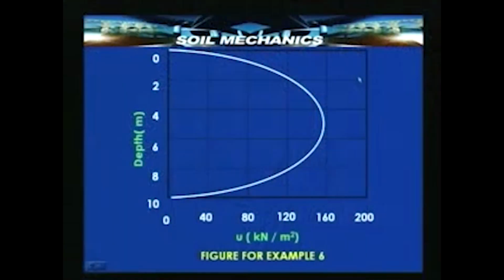So, now the pore pressure that is dissipated so far is on the right side of this curve, because this total area must represent the area corresponding to u equal to ui. This is the value of u that is existing now, and whatever value is here up to this between ui and this, that represents the value of excess hydrostatic pressure that has already been dissipated.